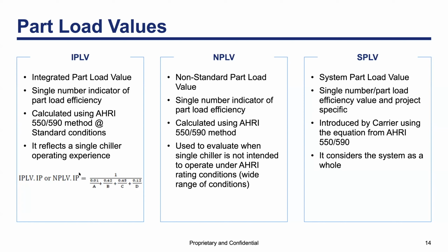That's the reason why we bring the last box on your right, the SPLV. The SPLV stands for System Part Load Value, and it was introduced by Carrier using the same concept from the AHRI 550/590. This is the energy analysis I was referring to before, since neither IPLV nor NPLV provides a really comprehensive energy analysis of the system.